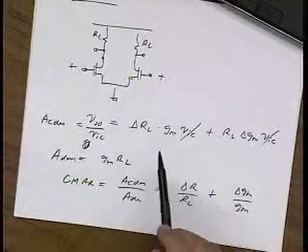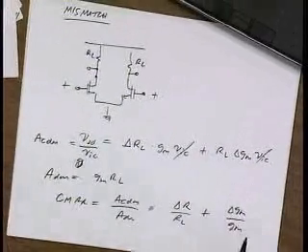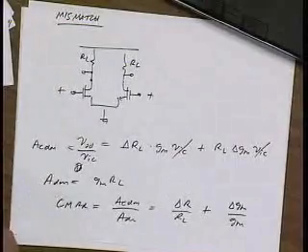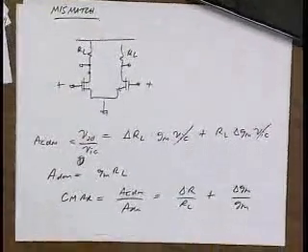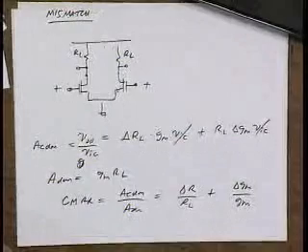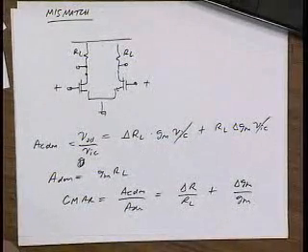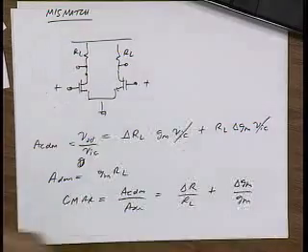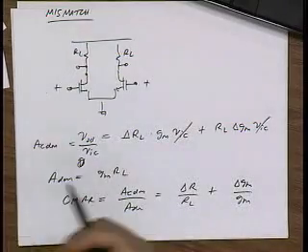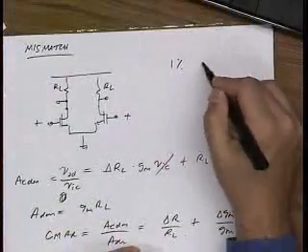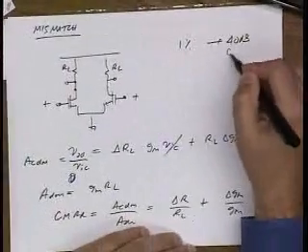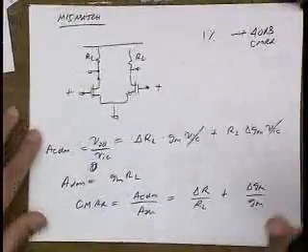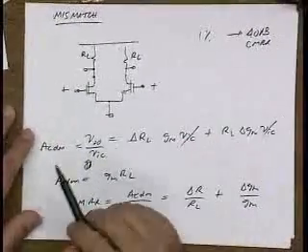So now this circuit's common mode rejection ratio is just a function of matching. So if I tell you you get 0.1% matching, what's the common mode rejection ratio? 60 dB, right? Very simple. So for instance, if I have a 1% match, then I would have 40 dB common mode rejection ratio. So that's why I put a current source here, right?